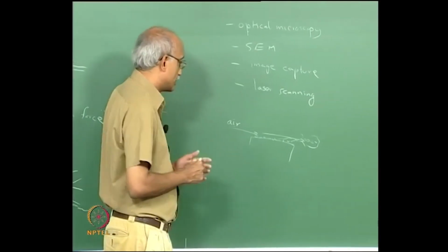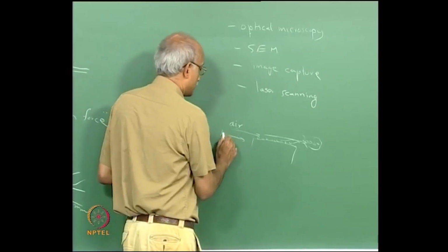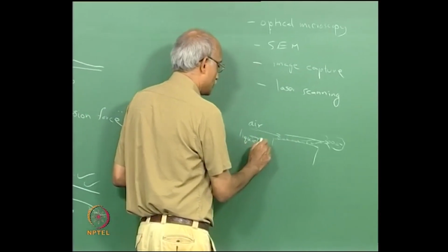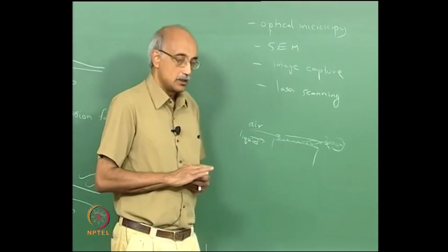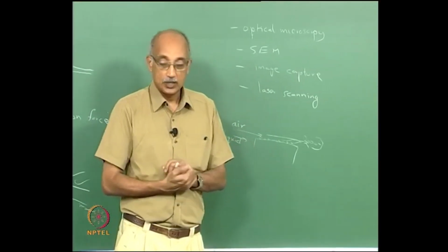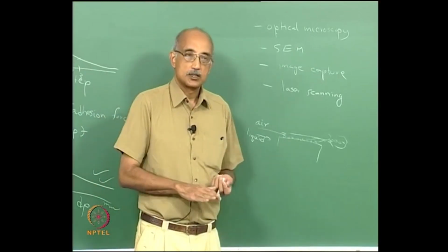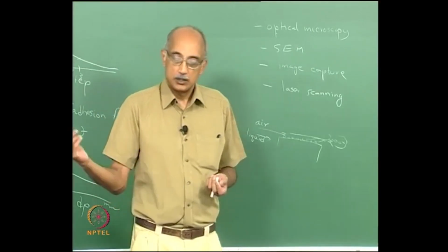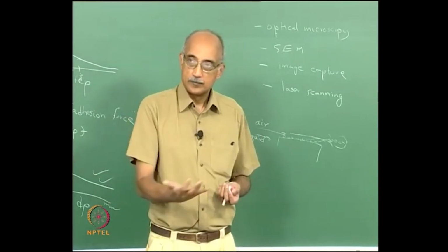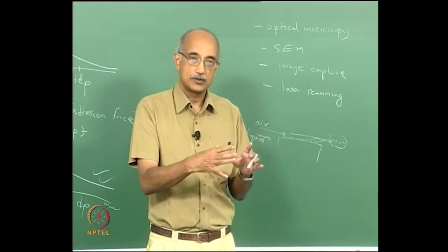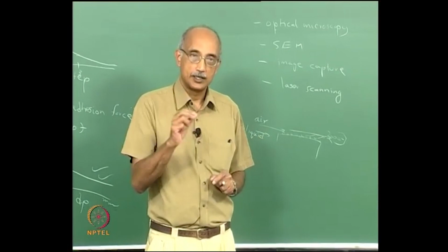Alternatively, you can do this with, for example, liquid spray. You can imagine again a surface like this, and you want to know how many particles there are. Instead of trying to measure particles on the surface before and after, you clean it with a liquid and then collect a sample of the liquid and count particles in the liquid.